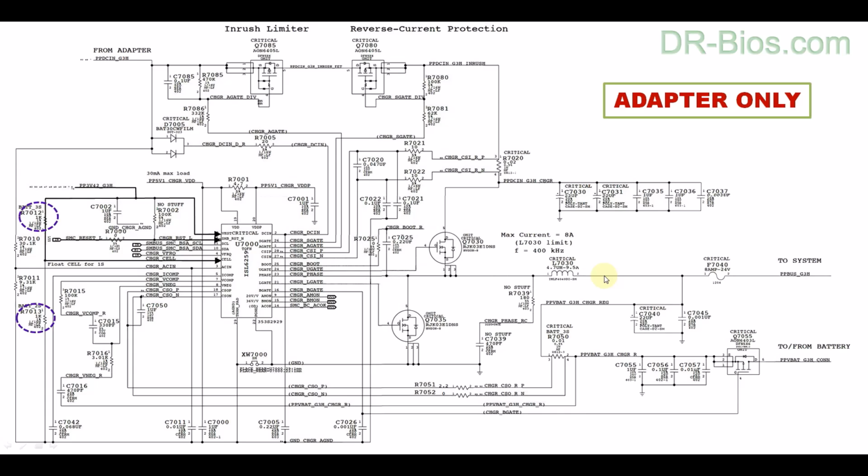So the voltage will be lower or higher than 12.6 volts in this device. So if you repair a device that has lower or higher PPBUS_G3H voltage than standard, one of the things you should do is to check these two resistors, which you should see if the ohm is correct or not. Sometimes ohm of these resistors change due to water spillage or sulfated problems.